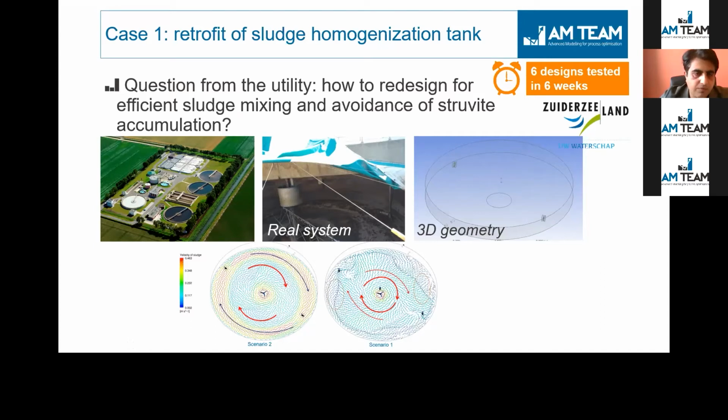If you look at these 2 figures, on the right side you actually have 3 impellers. So 2 side impellers, and 1 in the middle, in this case as well. The only difference from the right to the left figure is the angle of the outer impellers. The moment you turn the impellers in such a way that they start synergizing together, the central impeller and the flow caused by the outer impellers synergize with each other. So they are not counter-flowing against each other. In the right example, there was a counter effect, and the left is more in synergy. You can see it actually in the next slide.